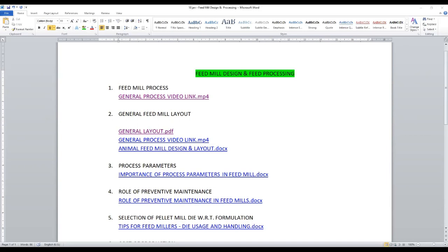So if we are assuming 100 feet width, then 42,000 divided by 100 is 420. So for 7,000 metric ton of grain and a 10 ton feed mill and 500 to 700 metric ton of the finished goods, we require 100 by 450, 100 in width and 450 in length. That is the warehouse we require to store that much material.